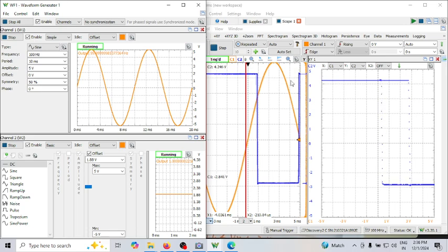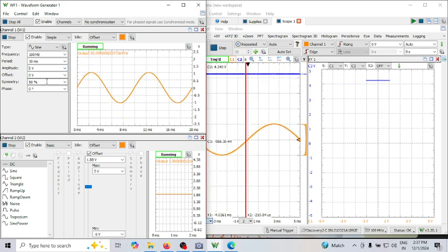So that's why in this particular Schmitt trigger experiment, input amplitude should always be greater than the magnitude of the maximum of VTH and VTL. It should be the absolute value maximum of VTH or VTL. So this is an important thing. Even if everything is fine, suppose you have simply applied a lesser amplitude, you will not get the output because your input is not crossing the threshold. So when your input is not crossing the threshold, the output cannot switch from the plus V side to the minus V side. It's a simple common sense concept. Thank you.